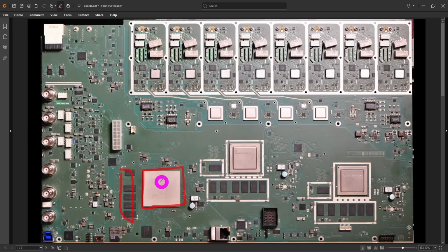Now, this is going to interface with these custom ICs on the right side, gather all the data, process them, and of course, do all the firmware interactions to the outside. Now, looking at the rest of this board, it becomes really obvious why it is so difficult to compete with manufacturers who make their own ASICs when developing instrumentation, like Rohde & Schwarz, Keysight, and Tektronix. A lot of the front end and a lot of the capabilities of this oscilloscope are because of the custom features inside of the ASICs.